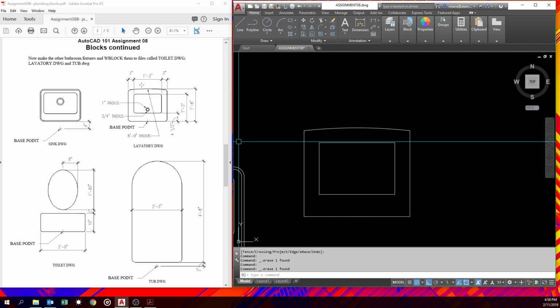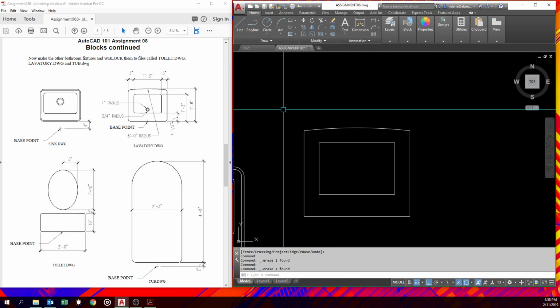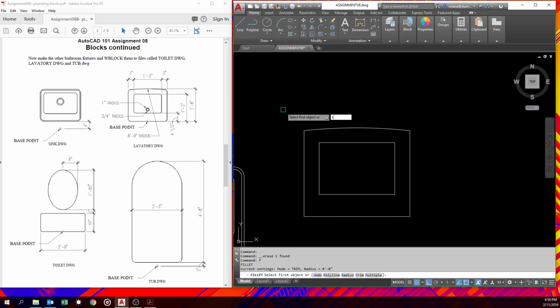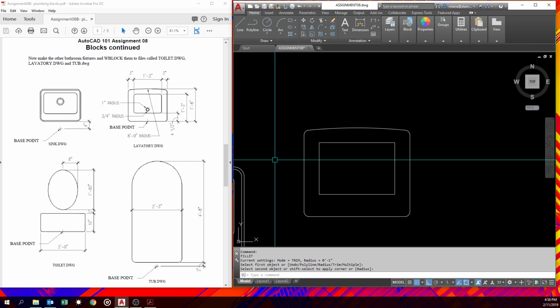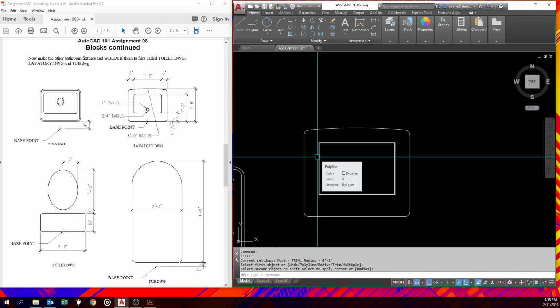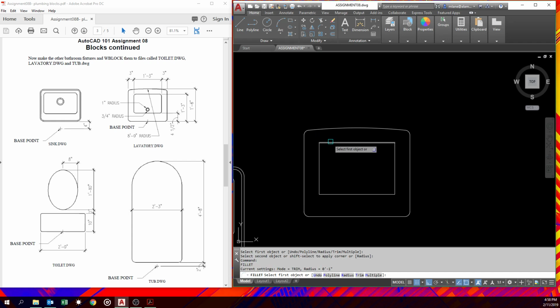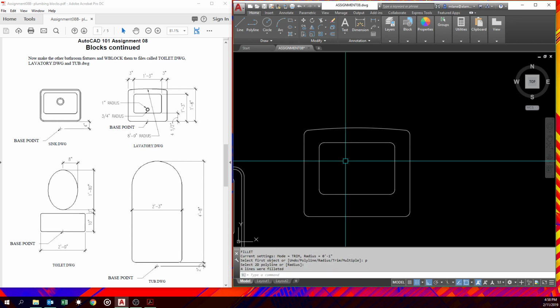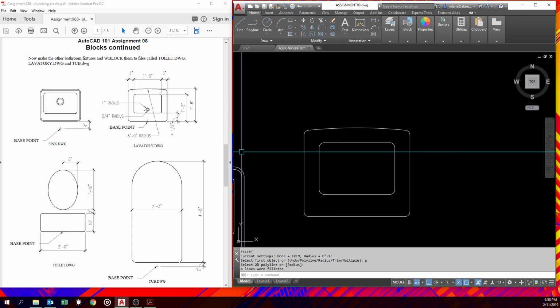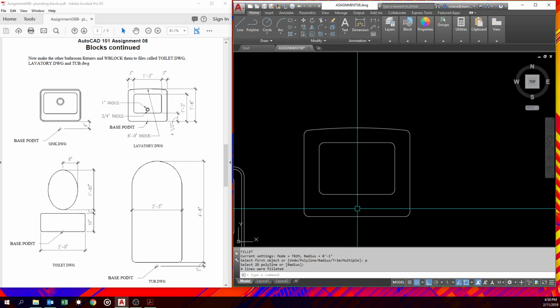And then just pick a radius. Let's try that 1-inch radius. So fillet, radius 1. Pick our things. Yeah, that looks pretty good. And like I said, for this kind of stuff, yeah, that looks pretty good is a good answer. So we'll start fillet again. And this time remember the polyline option. And we're good. We don't have a location of exactly where this is. We know how big they are. We don't know where it actually goes.